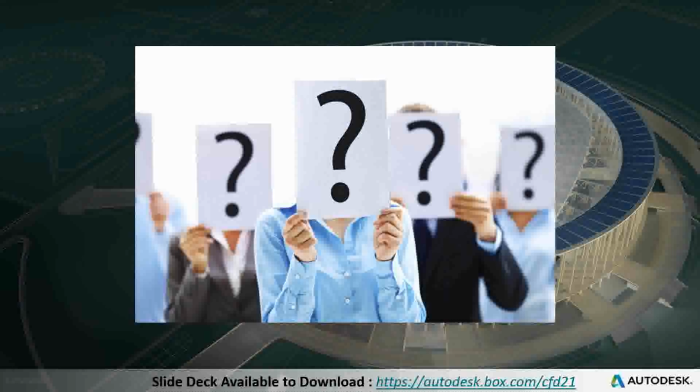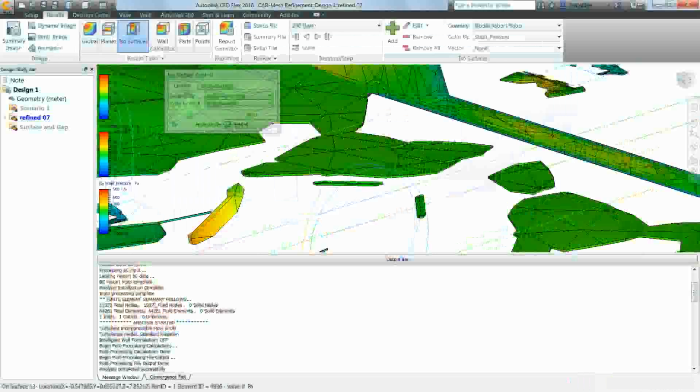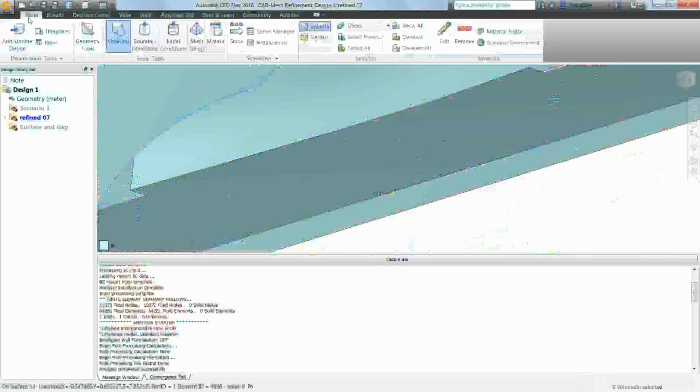I think you did a good job with the, just to throw out a little bit more reference, it would be good for people to look at what the turbulence models are actually doing. Like the big difference between SST and K epsilon is the wall function that's happening in the enhancement layers.